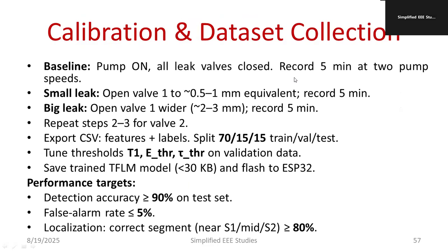Later you have to open the valve and create the fault condition. Small leak: open at least one valve, 0.5 to 1 millimeter equivalent, record 5 minutes. Then big leak: open the valve in a wider range. Because if you use the valve, you can easily control it, right?